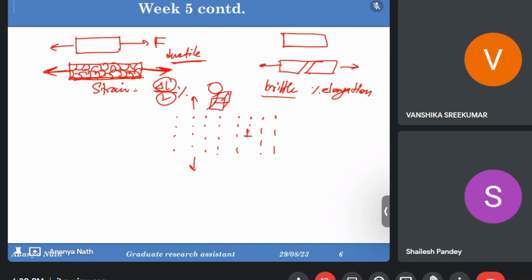Understood, ma'am. Ma'am, one another question. Sir said in the lecture, if we are using two digits, if we are using H for non-heat treatable alloys, like the 5 series, the first digit indicates, like H1, that the alloy has been strain hardened, right? And the second digit indicates, like 8 means 100% hardened and 4 means half hardened. But if there are three digits like 5083H321, the 3 indicates strain hardened first and then stabilized, right?